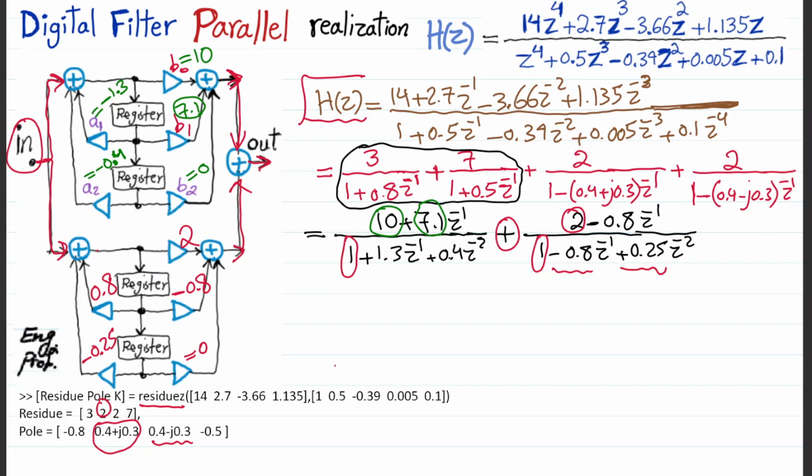All right, so as you can see, using just partial fraction expansion realized by utilizing Matlab's residuez function, then properly translating the reported values of residue and pole back to the parallel structure, we managed to find the proper second order systems that are added together to realize the H(z) given to us, and then use the found coefficients to program the parameters of the parallel structure as discussed in this example. I hope that this is helpful.